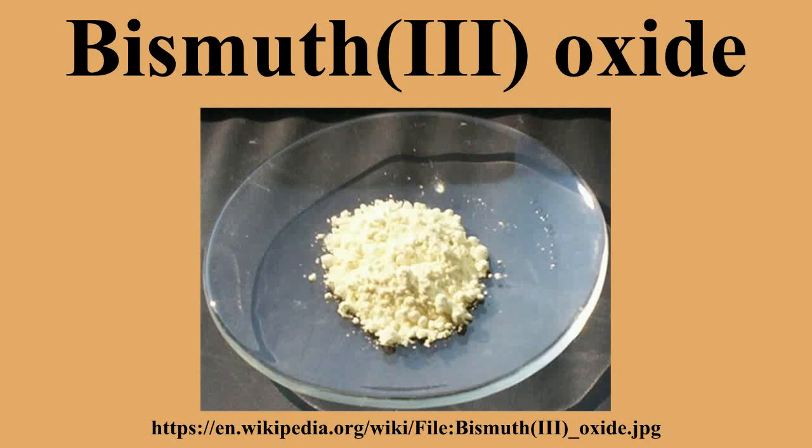It can be prepared by hydrothermal means and transforms to the alpha phase at 400 degrees Celsius. The monoclinic alpha phase transforms to the cubic delta bismuth trioxide when heated above 729 degrees Celsius, which remains the structure until the melting point, 824 degrees Celsius, is reached.